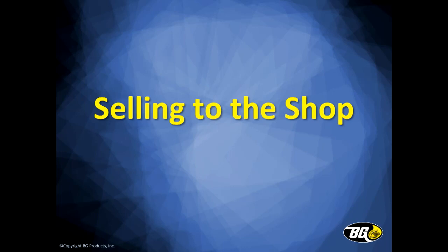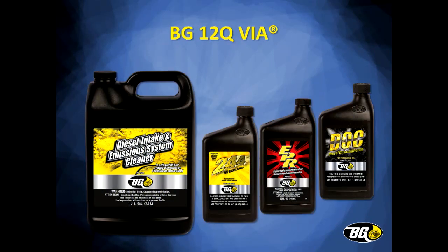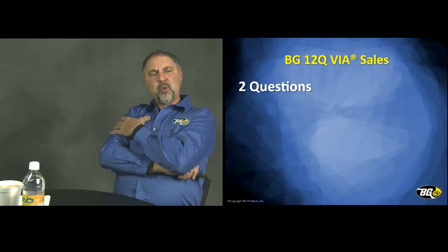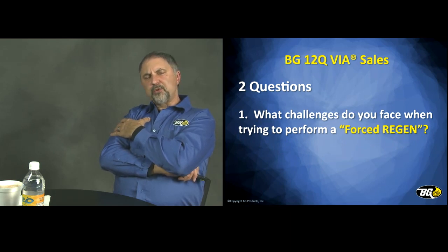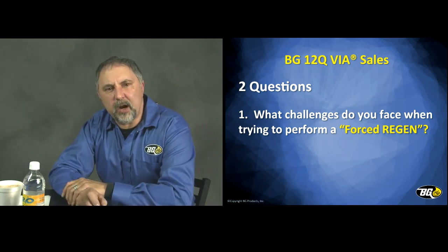I want to wrap this up, selling to your shops. The first one we're dealing with is the kit itself. I've always asked two questions. The first question I ask my shop is, what challenges do you face when you're trying to force a regen? I sit there and I listen to them. They'll tell you things like, I have to have it outside at 2,500 RPMs and it sounds like a jet engine.